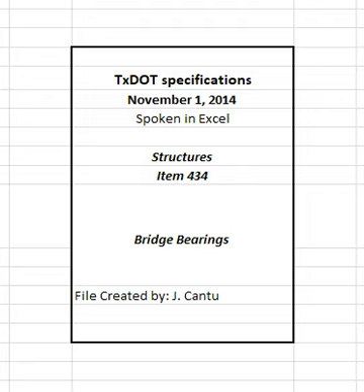Guided expansion configurations allow rotation about the horizontal axis and horizontal movement in one direction as indicated on the plans, while guide bars and keyways restrict horizontal movement in the orthogonal direction. Provide either disc bearings or pot bearings unless a disc or pot bearing is specifically required on the plans. Provide a fabricator-designed HLMR bearing meeting the performance and dimensional criteria described on the plans and Section